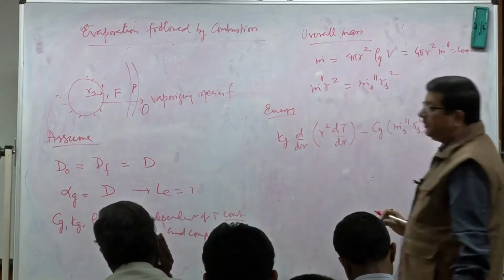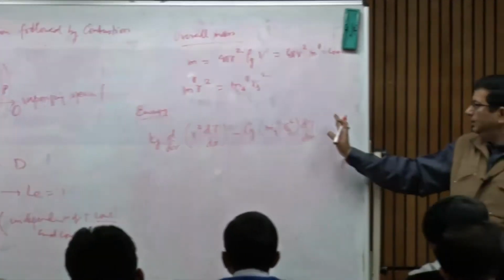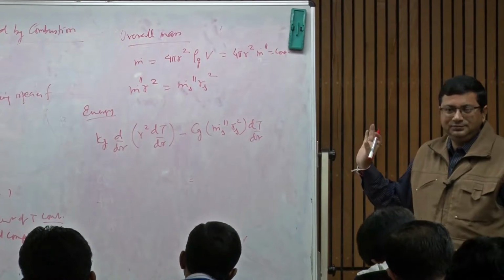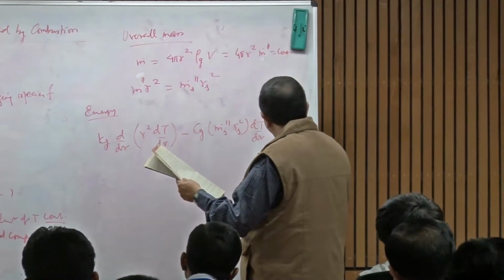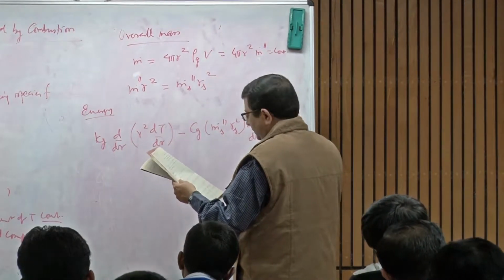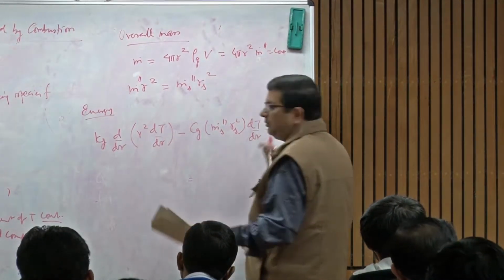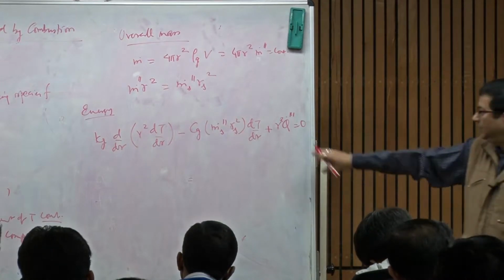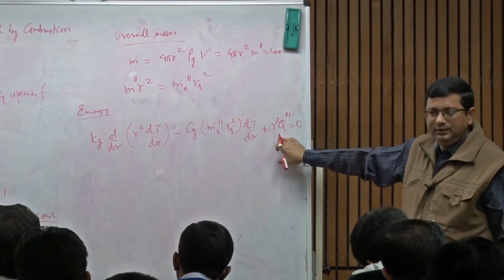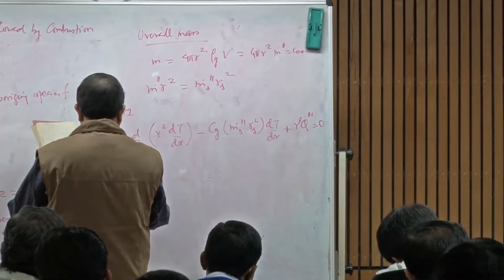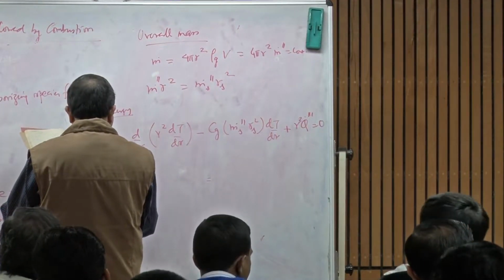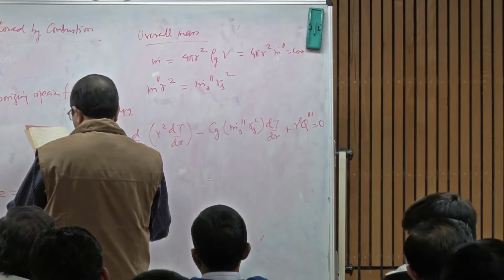In the previous case, when there was pure evaporation, this was equal to 0, right. But now, we have heat added because of chemical reaction. So, this term will come in. This term was not there in the pure vaporization case. Okay. So, this will imply Kg can be written as rho g alpha g Cg